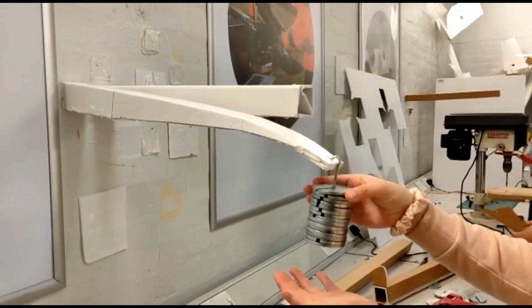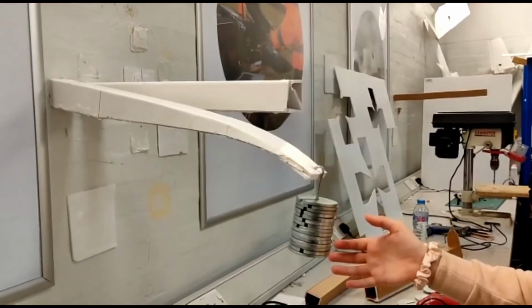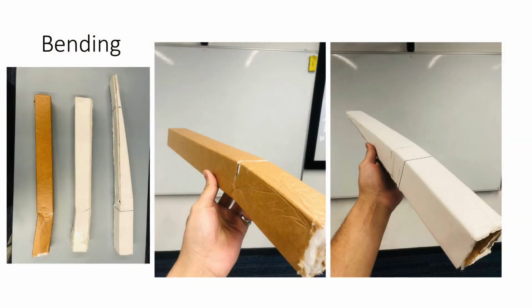We also experimented with tapering the spar, but in the bending test, we found that tapering would greatly reduce the tensile stress as it would bend much more with less mass added. We found that tapering the spar would decrease the build quality of the final wing, so we decided not to use a taper in the final design.